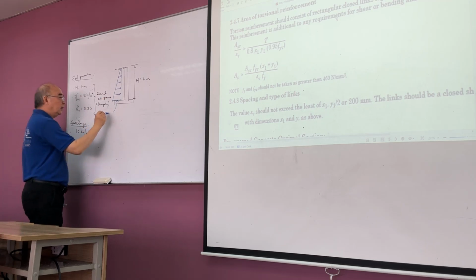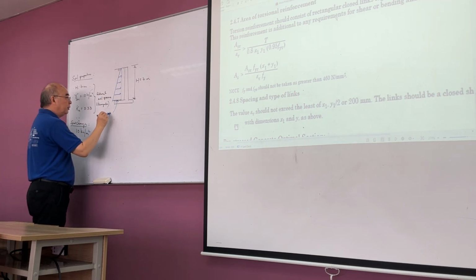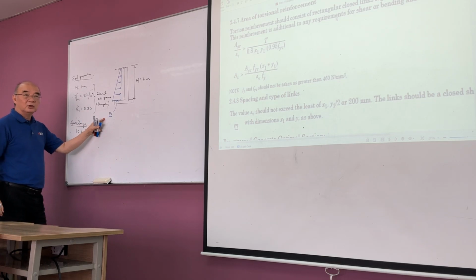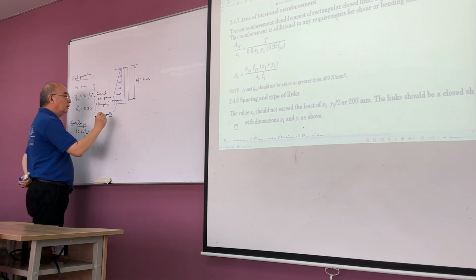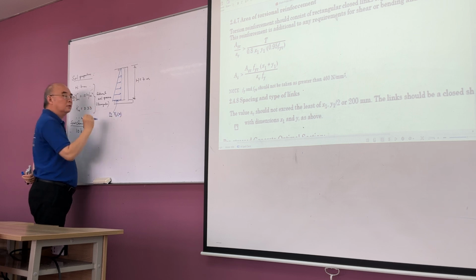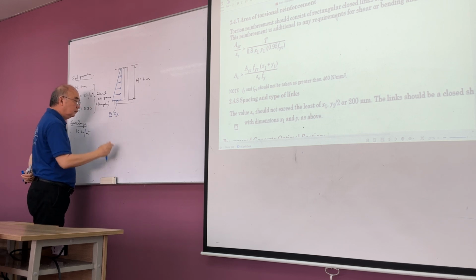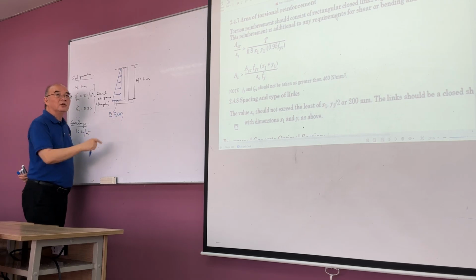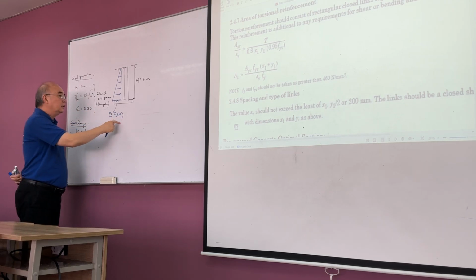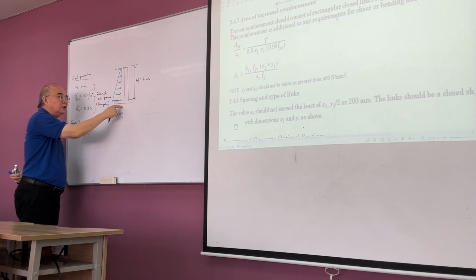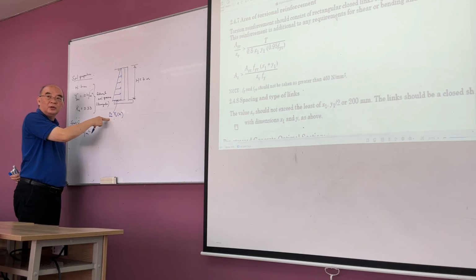Okay, so let's say this is p maximum, maximum pressure, small p. Small p is what? Gamma times H, because it's linear to H. As H is increasing, the pressure is also increasing.